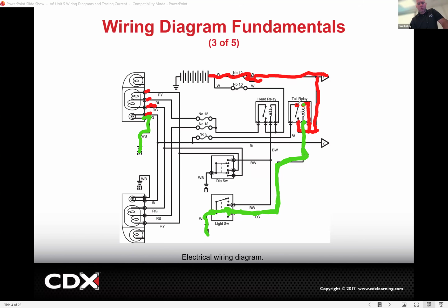Magnetism, which is going to close the relay, which then means red will go like this, go through the fuse. Should it drop anything through the fuse? Not really. It should still be 12 volts-ish. Go to here, go to here, go to here, go to there. But it also goes out this way, like we were saying before. It also goes down. So if you had a problem with those rear parking lamps, this is pretty much what you would do. You would trace it just like this.